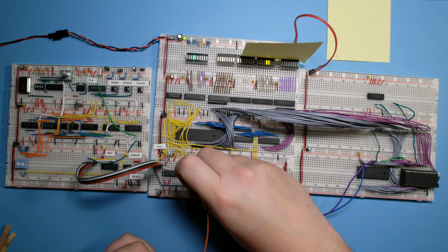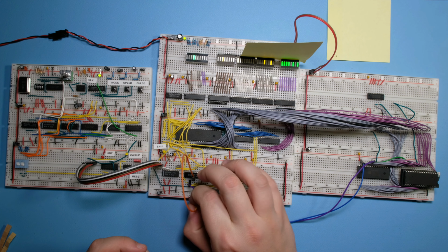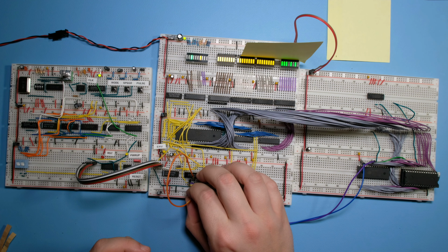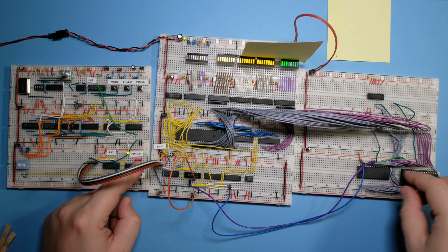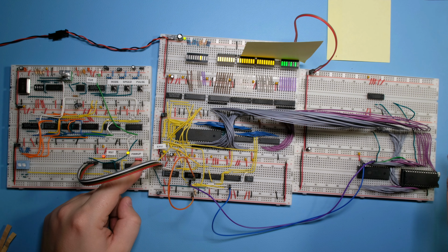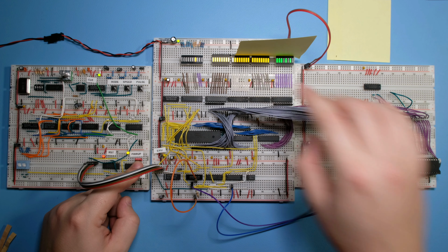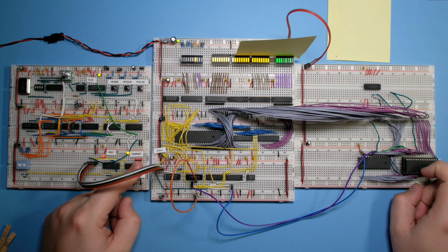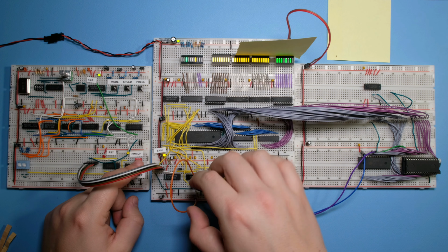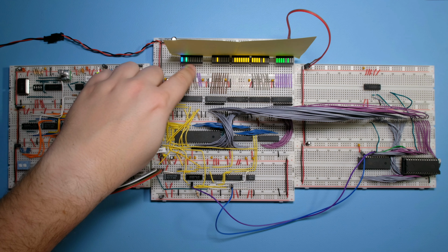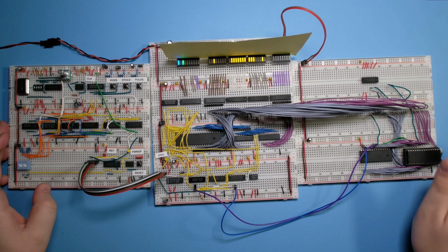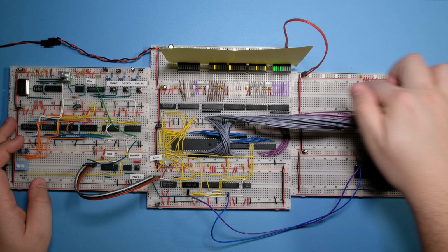Let me just check the polarity of my pull-ups by disabling the bus. Yes, so the address is all ones. And this shouldn't be driven now, because I taken bus enable low. Oh, I think what's happening here is, since my read pulse is not linked to bus enable, the ROM is still outputting here. So we need to fix that in the next episode, but the rest of the circuit seems to be working fine. There you go. So now we have proper colors here. And we can move on to implementing the address decoding.